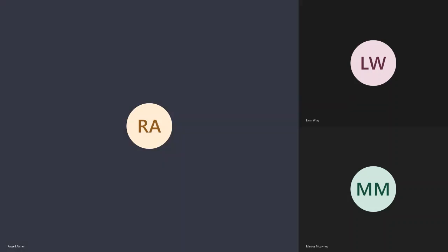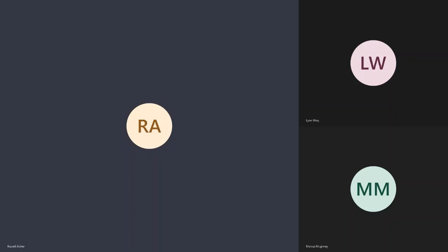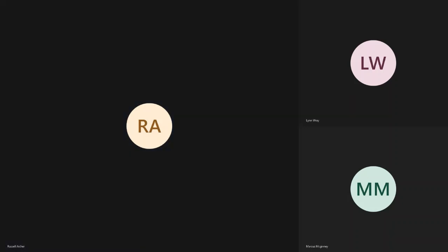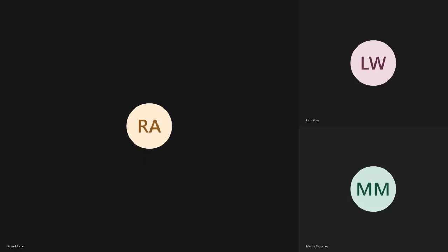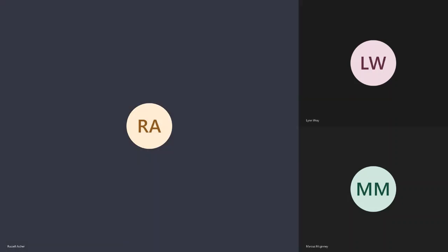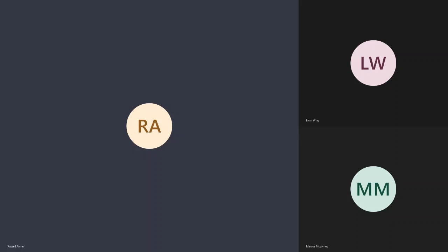Some things are more difficult. Some things are easier. Some things are more difficult than raster. So buffers are simple. You can't do cost path, which is what I'm having to do the digitizing for, because you're limited to only the features. If you have white space, white area between your polygons, the software can't do anything with that. It can't make the connection.